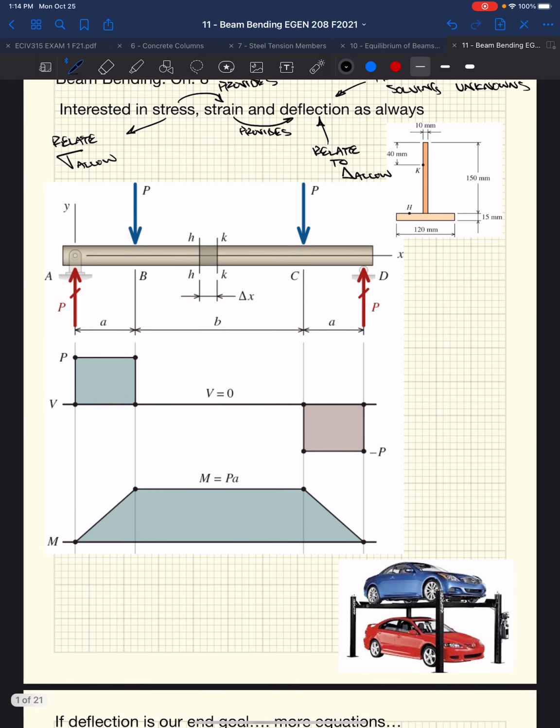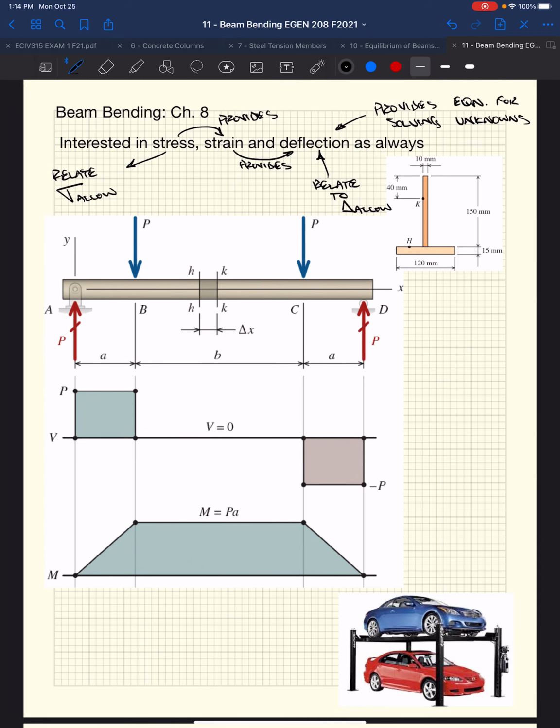An axle, like the axle housing, would be a beam, essentially, right? You've got essentially 2 point loads and it's supported on the leaf springs, for instance, right? So there's bending in that axle housing. All right, so if we had a beam here, had 2 point loads on it, simply supported, okay? And it had a cross section that looked like this, an upside down T.